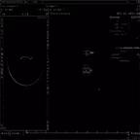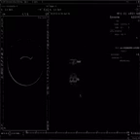VOPs come in very handy if you want to work with noise. So let's do this. Maybe it's a little bit easier to see what we want to do if we use a grid instead of a torus for this example. So lay down a grid, size it to 1 by 1, like so, and let's create a lot of subdivisions, let's say 400 by 400, such that we have a lot of points.